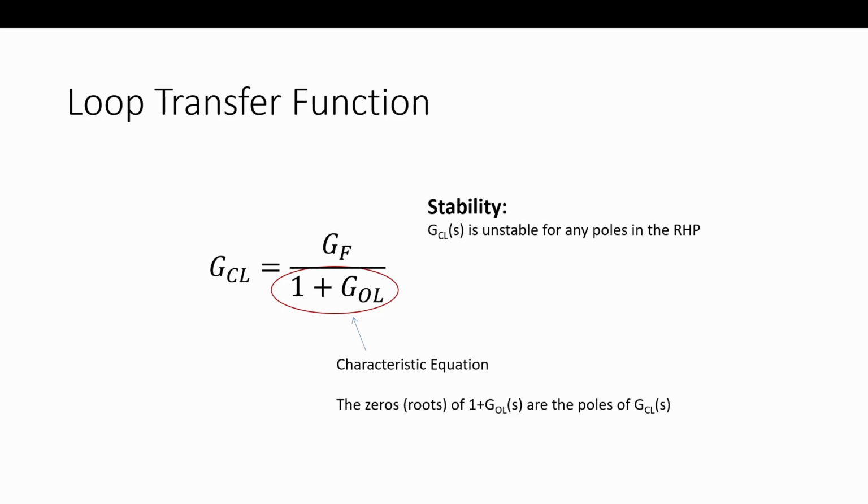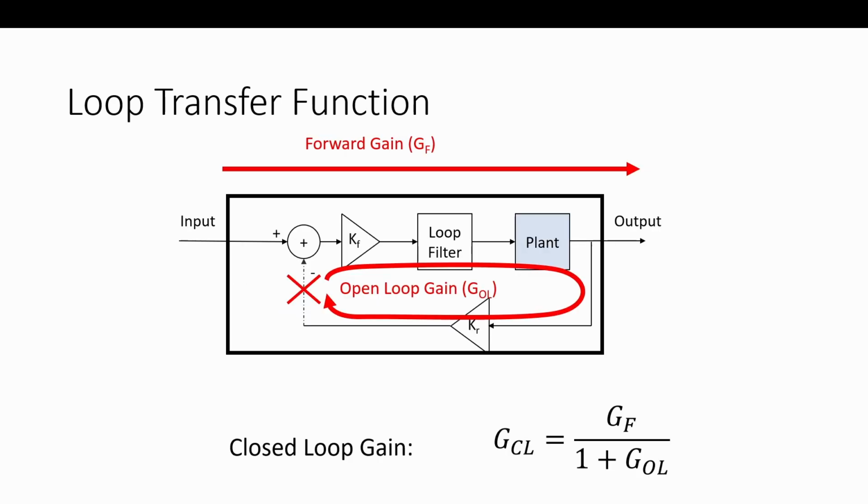And then we have the forward gain that we can, as I mentioned, choose any input to any output. So in this case, the input was here to the output. But in the examples we'll see, we can have an input right here, such as we saw a VCO. It could be the VCO phase noise, modeled as noise coming in on an output node. And what is this two-port system as a response to the phase noise and how it cleans it up and all that kind of stuff we'll see. So it's great for doing all that.